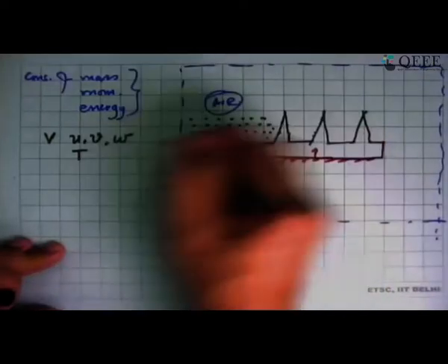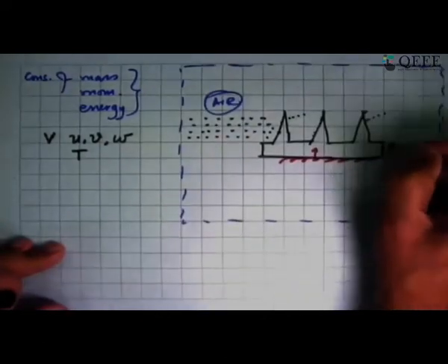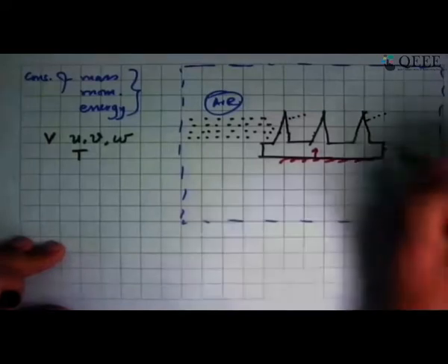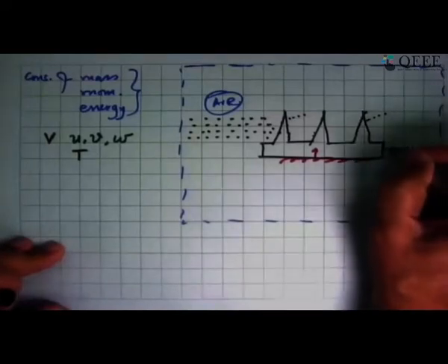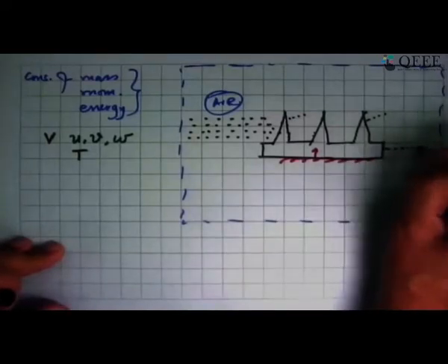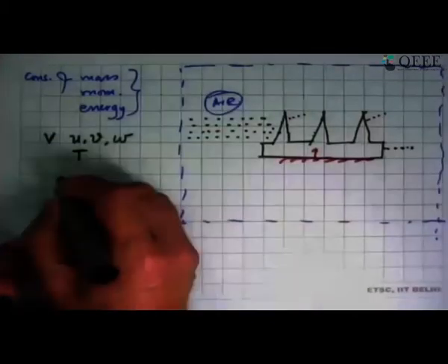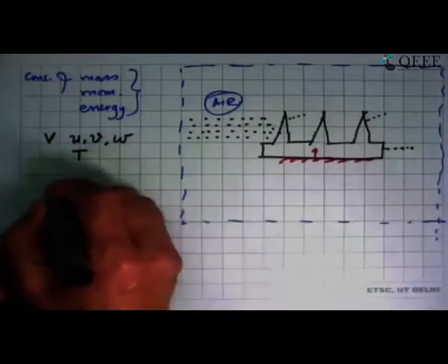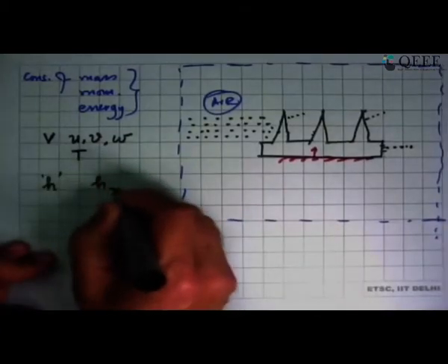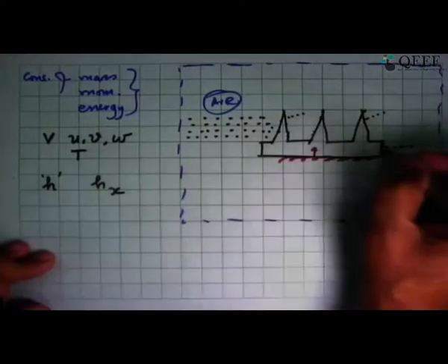The surface temperature was something, and that gives us the gradient of temperature normal to the wall. So I can get the temperature gradient here, the temperature gradient here, the temperature gradients over there. That means in this direction, the temperature here was this much, here is this much, here is this much, and here is this much. From this data, we go back and then compute the wall temperature gradient and get what the value of H at that point for a small area, and this we call Hx, which is a local heat transfer coefficient applicable to a small area.